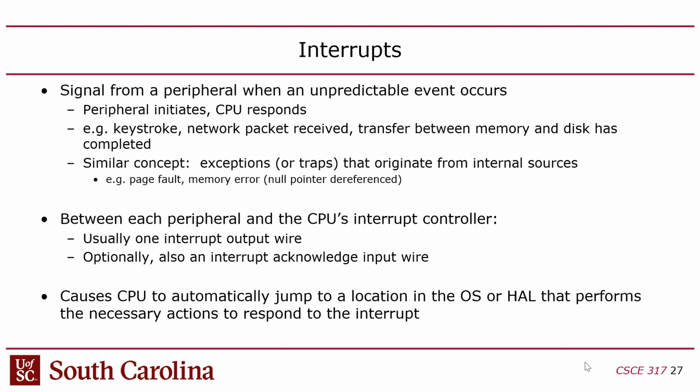The problem is that the interrupt generator and the CPU are asynchronous. They're two separate hardware devices. So you run into some issues when, for example, the interrupt sender gets a little too aggressive with the interrupts, you might end up live locking the CPU. You might interrupt it so often that it can't do anything else, right? That's the way a denial of service attack works.